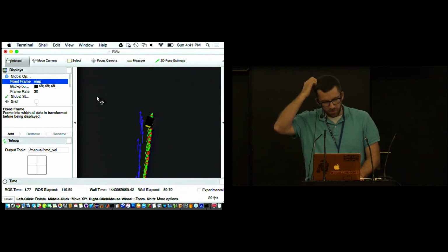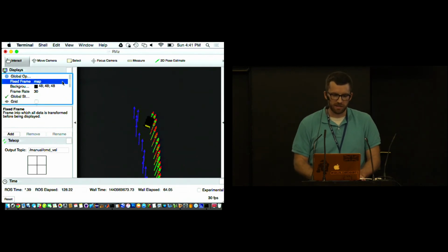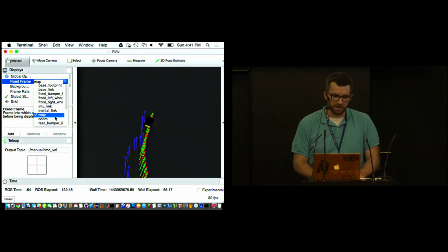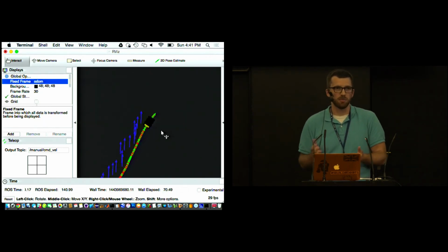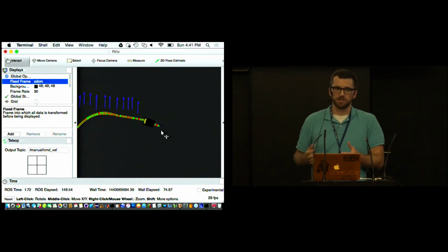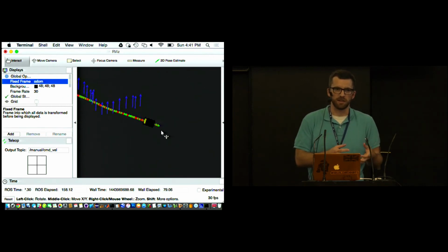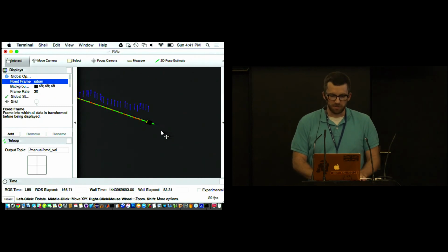It makes an important point, which is that one of the powerful things about Kalman filters in general is that they can deal with noisy, terrible data, and especially when you have a situation like this where perhaps you know that your IMU might not provide very good orientation data, you might have another IMU on there that does. So you can use them both, or you can turn the orientation off on one and use its angular velocity instead, just use the gyro data. So it gives you a wealth of options.